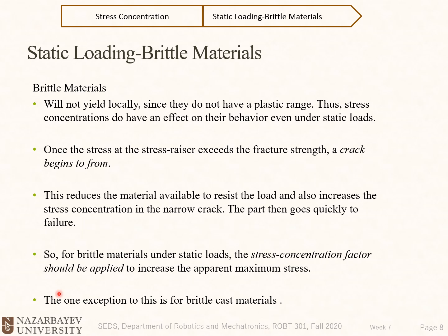This is another topic, but in general we could say for brittle materials, we must consider the effect of stress concentration, and we need to find the geometric stress concentration factors, Kt and Kts.